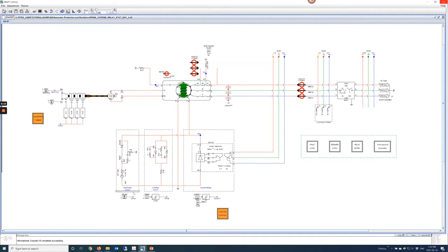For that reason, we have a circuit here called field flash circuit. And right at the beginning, we close this breaker on the field winding, to produce some current into the field winding and eventually some voltage. And that voltage can be used to be rectified and applied to the field winding.